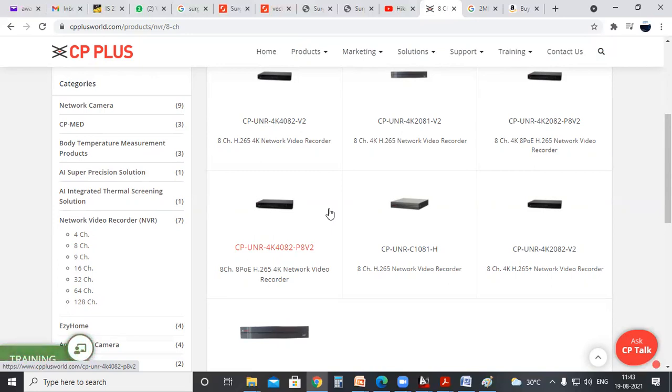Okay, so you need to understand, you can't provide it in a public, common space. So depending on the number of cameras, you have to select the appropriate specification. So up to 128 channel is available. That means even if you're having around 100 cameras, you can connect within the single NVR.